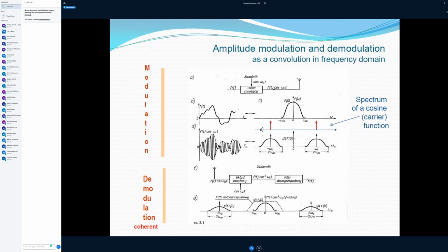And if we want to put the spectrum of our data in a given location in the frequency band, we have to modulate the carrier function. And we said that the carrier function usually, well, not usually, always, is a sinusoid, the simplest signal possible.